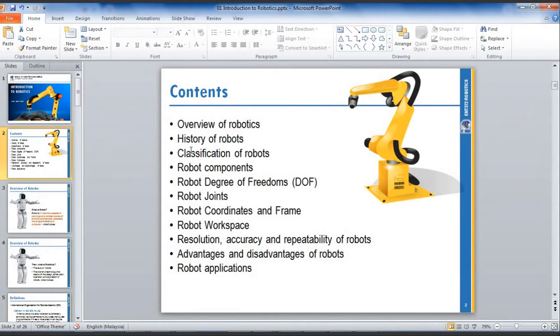One is homogeneous transformation matrix and the other one is DH method. Based on theory, DH is a simplification of homogeneous transformation matrix. For homogeneous transformation matrix, we use a 4x4 matrix,